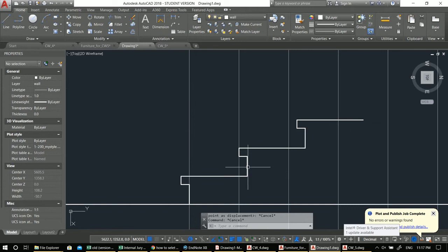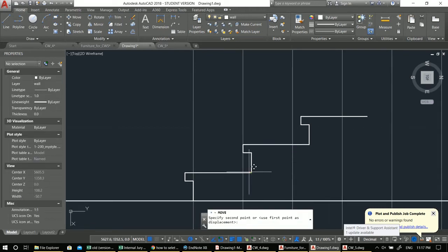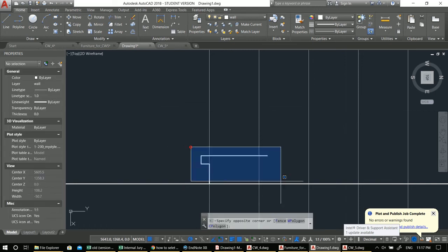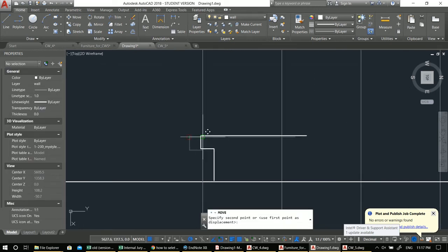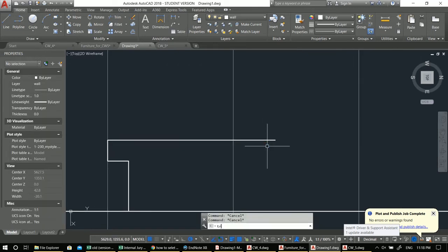I'm doing a mistake here. Yes, I'm doing a mistake here, because the line that it shows on the drawing is actually from here, so I don't have to go 5 centimeters. I'm already 10 centimeters in, so let me trim this extra part out, and let me offset this 5 out and extend that line. Alright, so sorry about that.